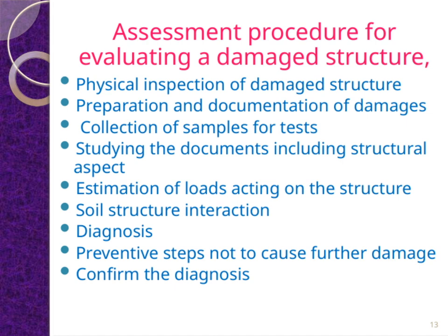Then comes the diagnosis phase. This is where we analyze all the gathered information to identify the root causes of the damage. Based on this diagnosis, we can determine the appropriate preventive steps to avoid further deterioration or failure. It's important to confirm the diagnosis through additional testing or analysis, ensuring our conclusions are accurate. Finally, we follow a thorough assessment procedure for evaluating the damaged structure, integrating all these aspects to develop a comprehensive understanding and plan for repair or reinforcement. All these steps are interconnected and essential for a reliable evaluation that supports the safety and longevity of the structure.